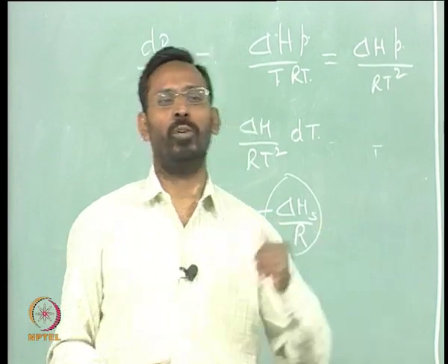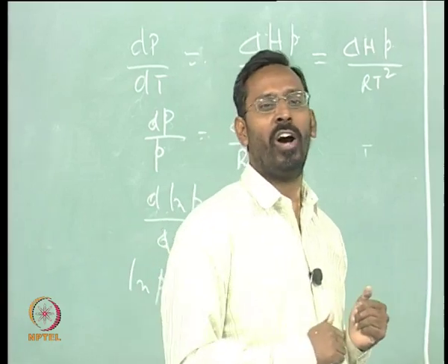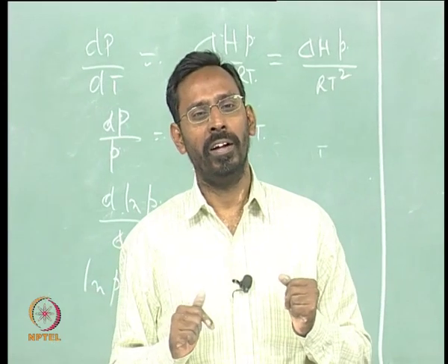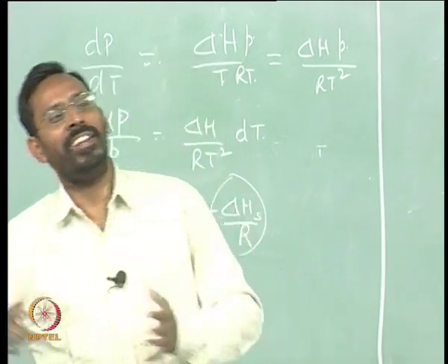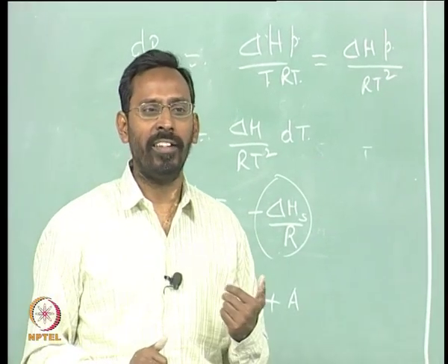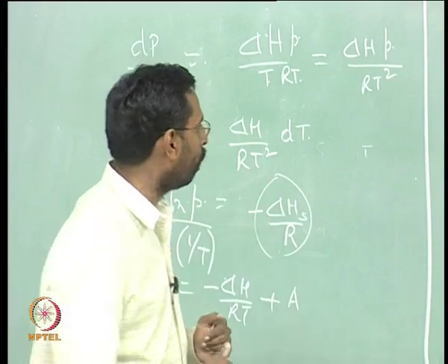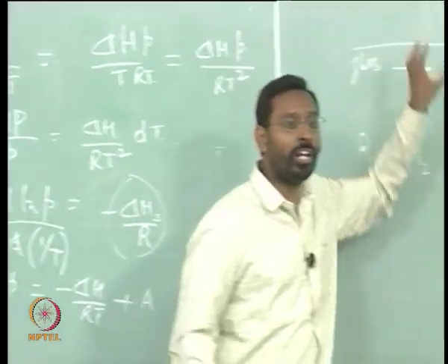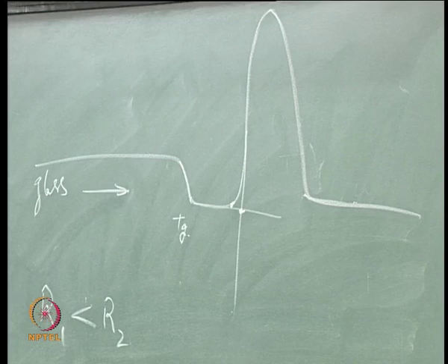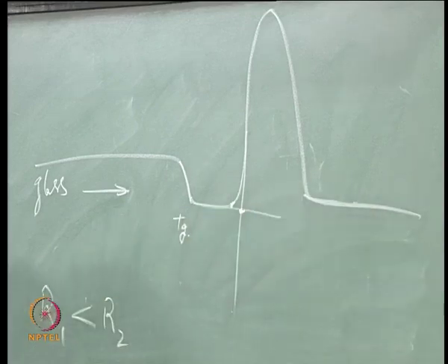As a result it undercools, whereas if you are heating a solid into a liquid, there is already a surface available, so it does not need as much activation as in freezing. But here it is again a solid to solid transformation. A glass crystallizing is not exactly like a liquid freezing. So you would see a significant shift to a higher temperature if the heating rate is higher.